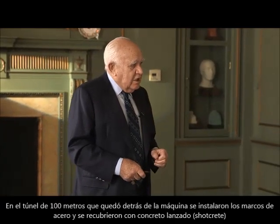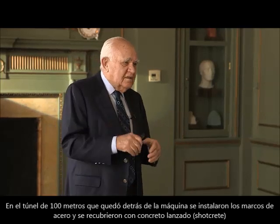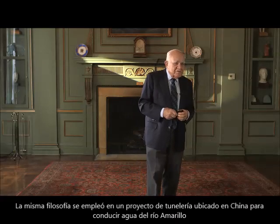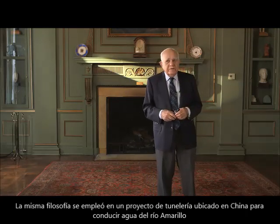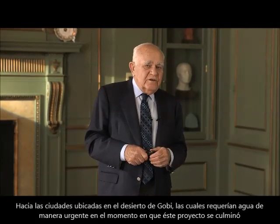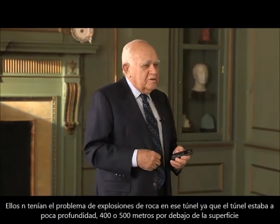The tunnel, about 100 meters behind the machine with a steel set installation, shotcrete lining was applied. So that tunnel, as I say, is complete and in operation. The same philosophy was used in a tunneling project in China to bring water from the Yellow River to towns or cities in the Gobi Desert, which require water urgently when this project was set up. And they didn't have rock burst in that tunnel.